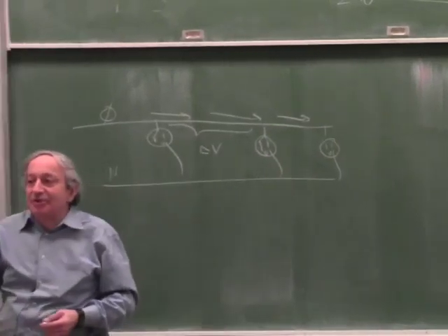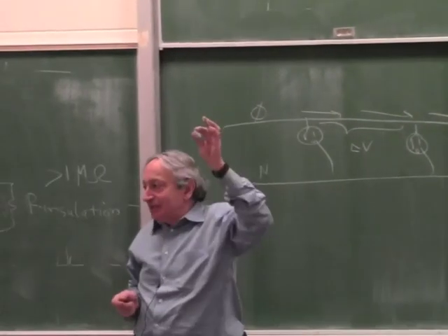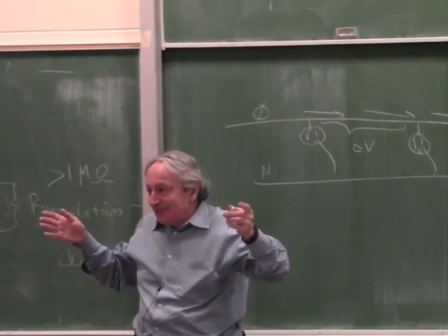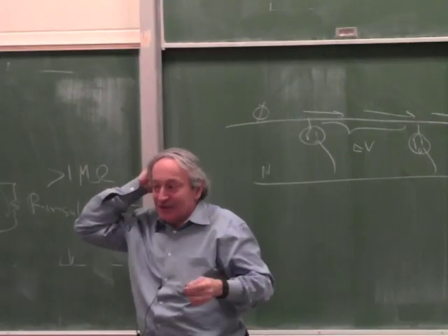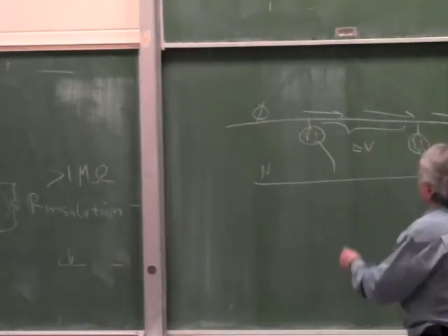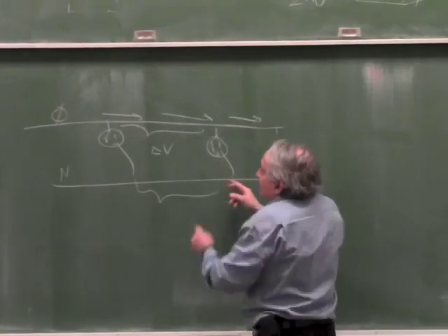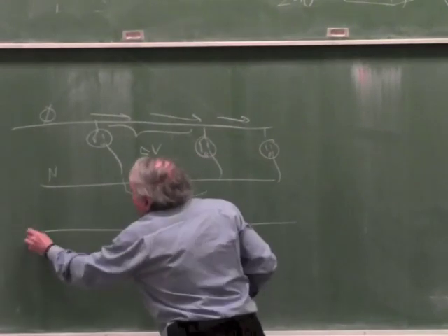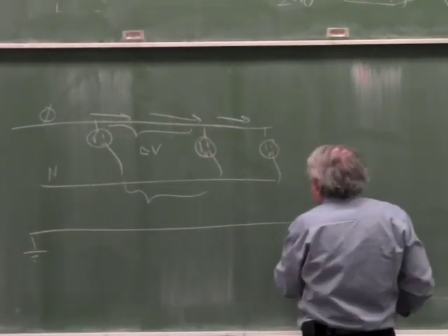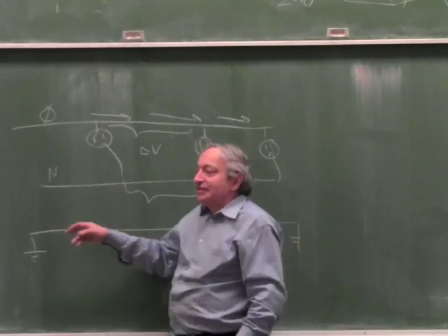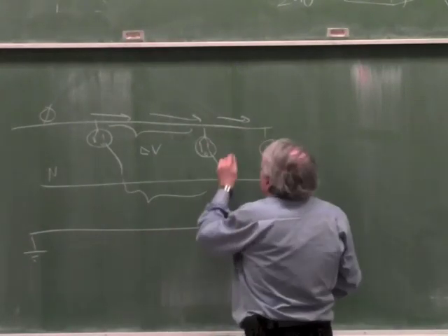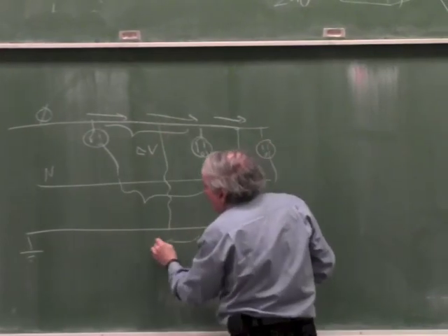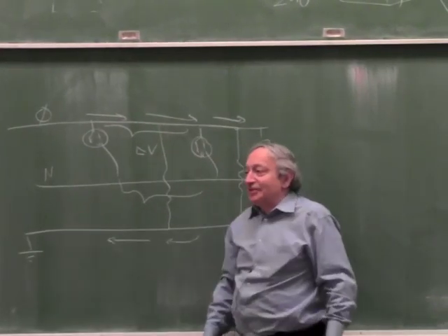And the best example, when you turn on your toaster, the lights dim. In especially old houses, lights dim, which means there must be delta V. Right? 10 volts at least. So I expect delta V between outlets, I expect delta V between neutrals, because it's the same as a phase, the same wire. But I didn't expect that the ground, which is supposed to be 0 volts, I didn't expect that there's also little delta V's along the ground because of leakages. There's all kinds of leakages to the ground which cause small currents to flow through the ground.